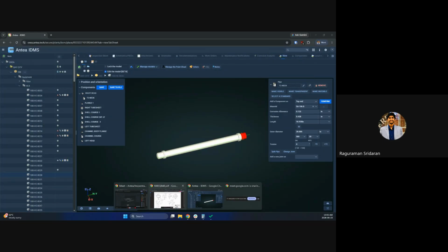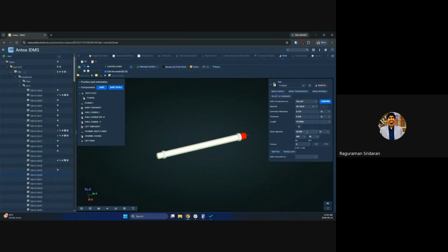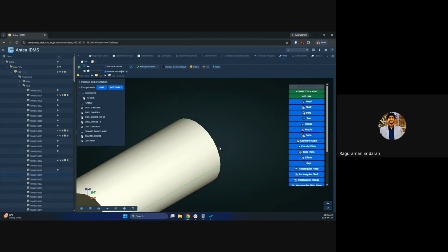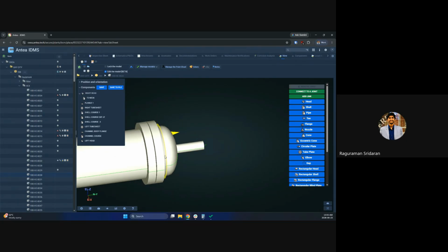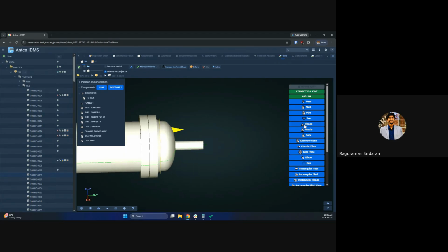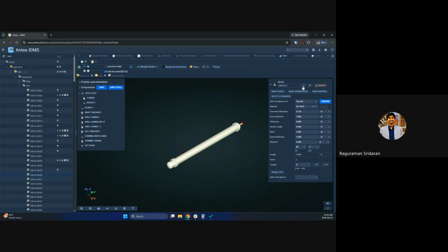Now we set this pipe size, 3 inch. Okay, so we say here 3 NPS, and we say confirm. And now we are going to create the flange. So usually when I create the body flange, I choose this flange component. But when I create the nozzles, I choose nozzle. You see there is a component called nozzle. So now we do the same.